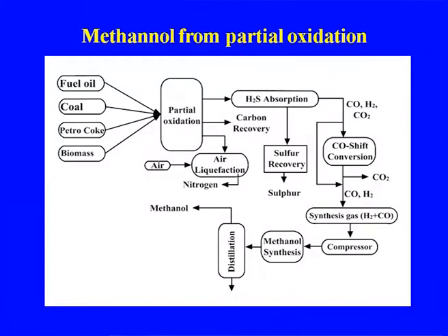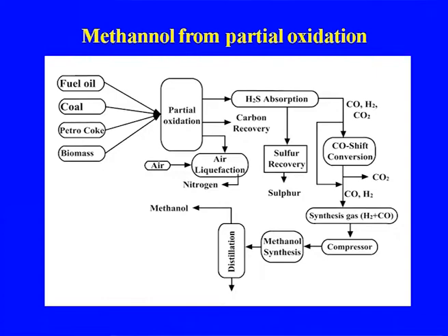This is also the same. If you are having the heavier feedstock, meaning fuel oil, coal, petcoke, and biomass, then the partial oxidation process is used there, and it will also go for the H2S absorption, because normally in partial oxidation fine carbons are also produced. So, the carbon recovery section, air liquefaction, because the air that will be required for the partial oxidation, this is oxygen, the reaction is like that.